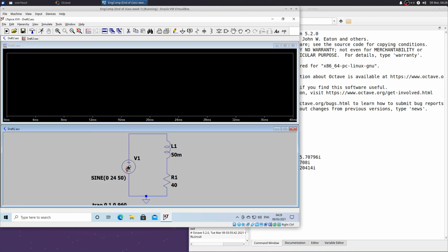As soon as I press OK, the simulation runs, and it brings up a blank graph, but we haven't specified which waveforms we want to observe yet. When you hover over the circuit diagram down here, you're offered 2 different tools. When you hover over an element, you'll see the current loop measurement tool, and when you hover over a node, you see a voltage probe tool. In this case, I'm going to plot the voltage waveform at the top node. That's the supply voltage, and you can see there are two cycles of the supply voltage.